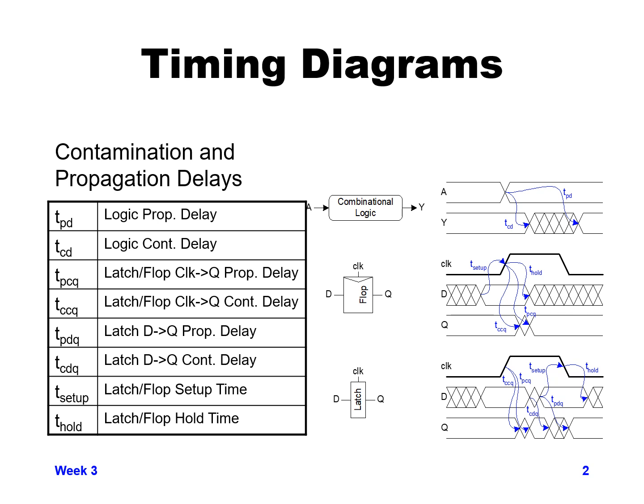Now in this particular case, we don't have a setup and hold based on the opening of the latch, because while the opening of the latch allows a value to go through, that's not where we ultimately decide whether the latch is going to capture and hold the value. While the latch is open, potentially the data could still change in the middle of the clock being high. So we see two additional edges based on the clock or the data changing while the clock is high in the middle of its high time.